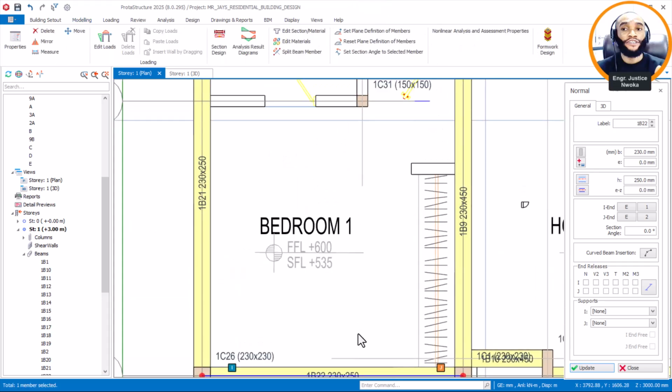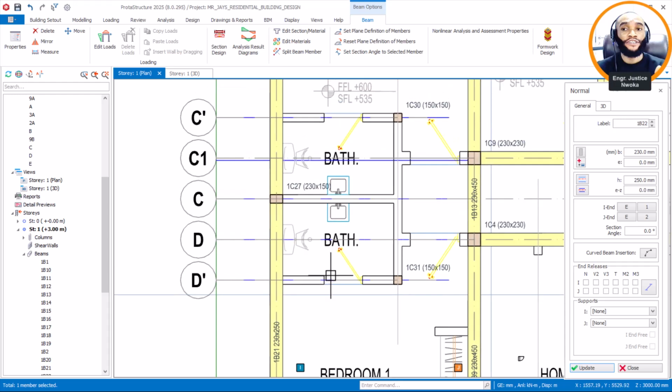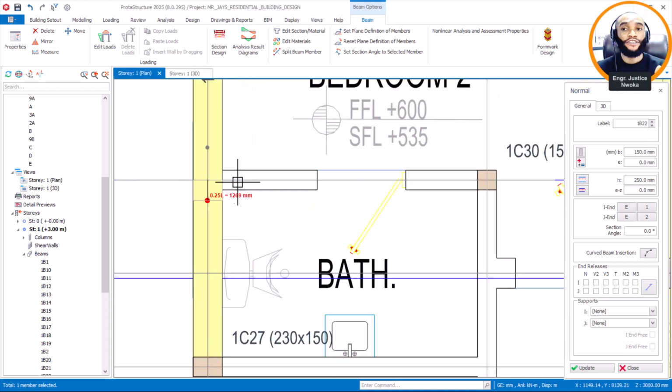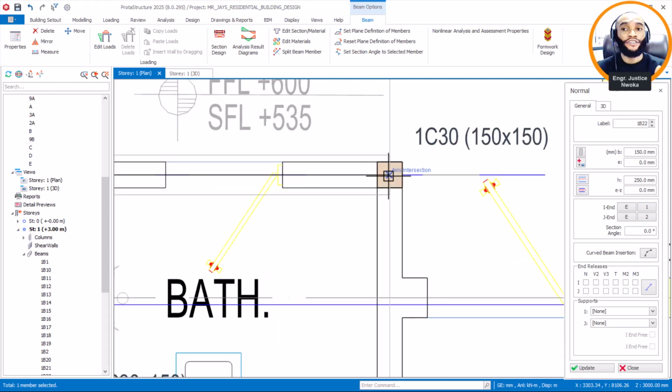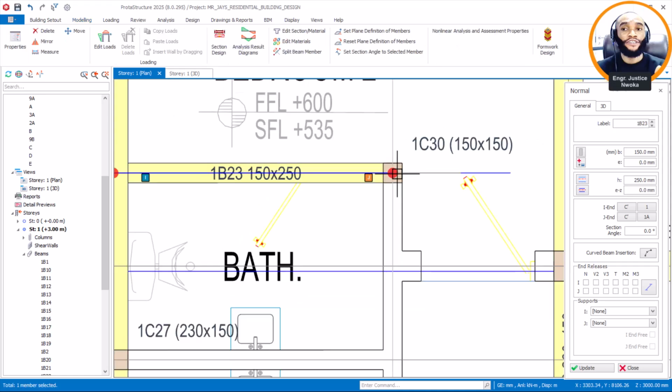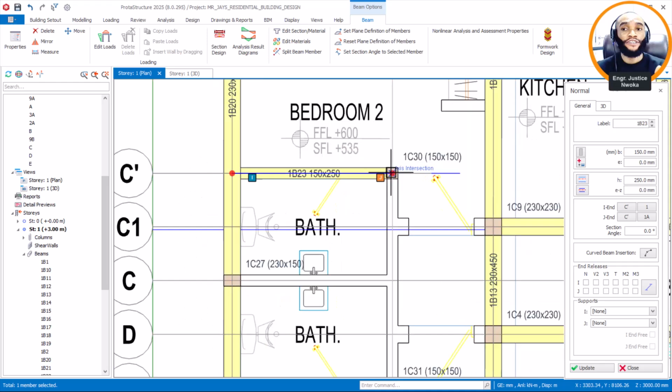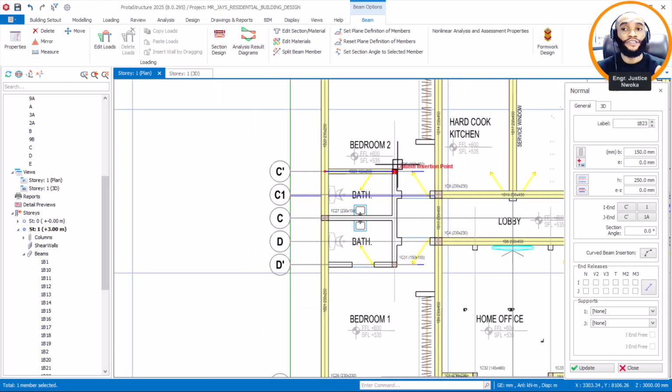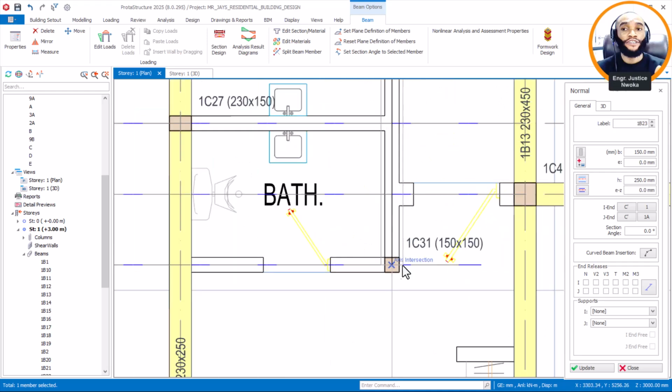Now we don't have a different beam width, because the beam width on this other side is 150. So I'll come now and reduce this to 150 beam width, because of the block wall here, and also it is not carrying any load. So this is like a lintel beam. All right. So this is like a lintel beam around this place, correct? That's fine. And also serving as a roof beam around this place too. So with that, I'll come here and just brace here up a bit.